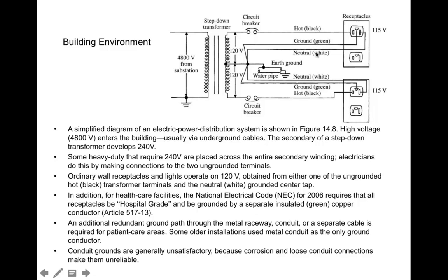But in more modern homes, or homes that have had new wiring put in, you will always have a 3rd plug, which is your ground. That ground is the earth ground. The neutral wire is also tied to the earth ground, but what the green wire does is it allows you directly from the earth ground to also ground the chassis and any metal surfaces that are present in the room.